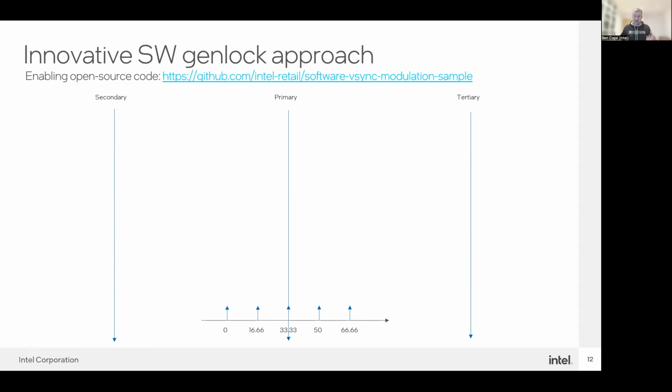So read those vsync signals, so we can essentially read how many frames have gone by on each of those, and then you can compare the count between the systems. And if you find your secondary system has output slightly more frames in a period of time than the primary one, then we want to slow down the clock output very slightly on that secondary system so that they come back in line. And of course, this is something that can drift over time, so we want to periodically do this. Satishwar, are you okay to talk through how the software stack works here for this?